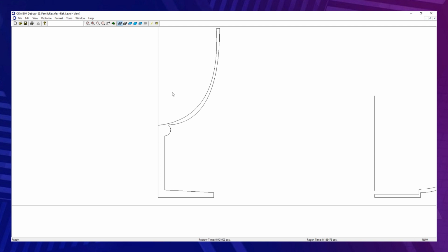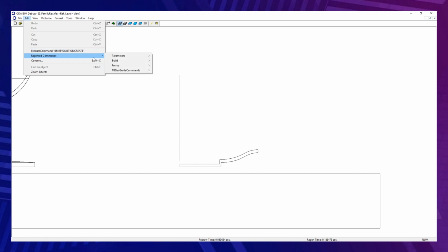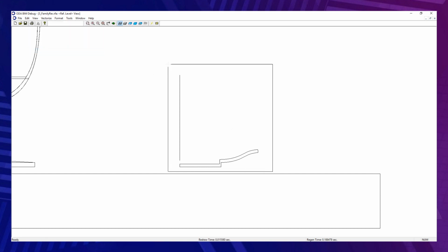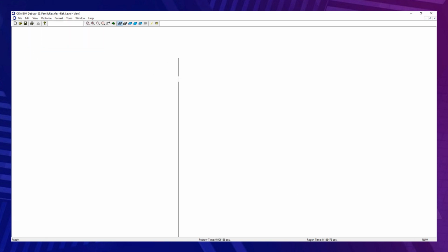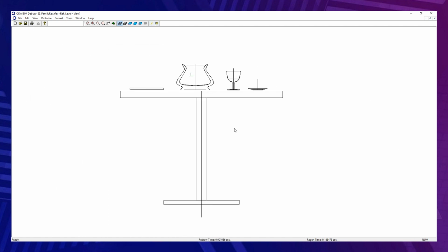This section works now also. Select an axis, start and end angles, and material name. And currently we created a scene with several objects of revolution and extrusion. Currently we will change the view to 3D.